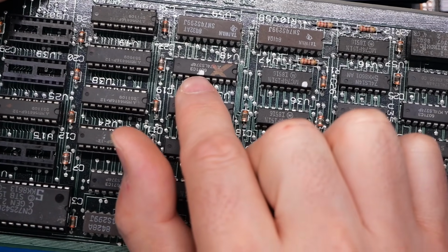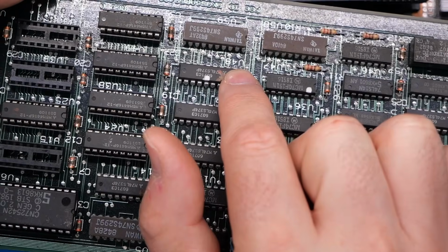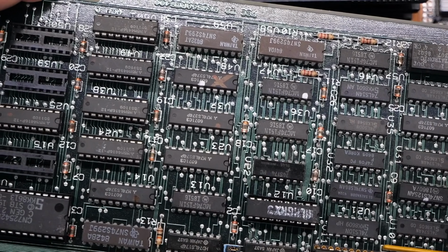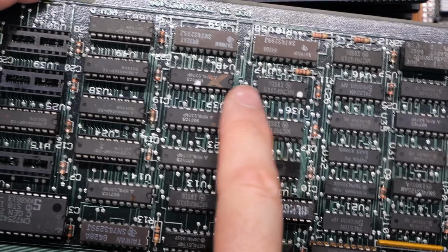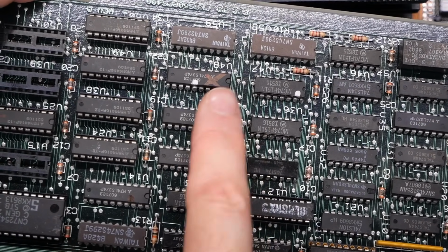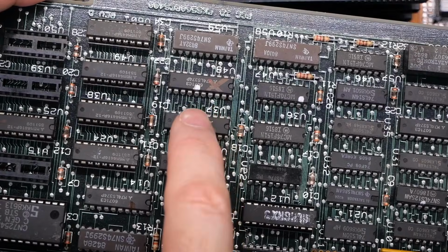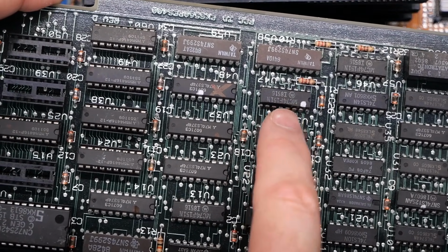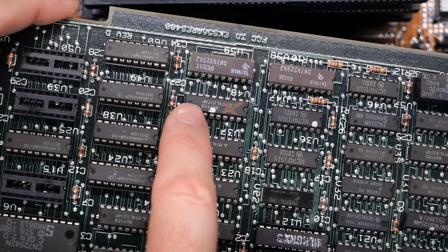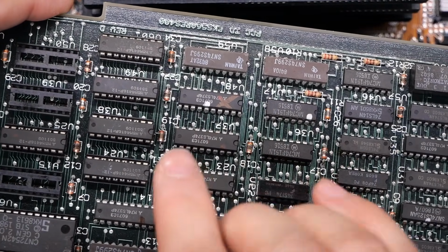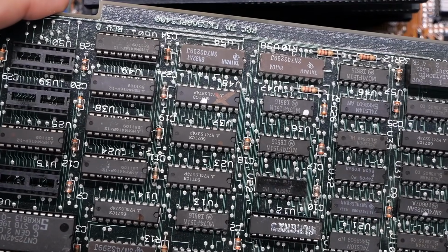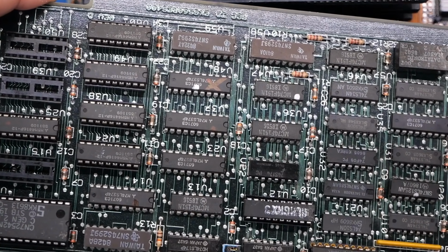One way we could actually test is cut the pin halfway up from the board, so you could probe the output of the flip-flop without actually removing it entirely from the board. That's just a good way to test, as long as you disconnect the connection between these two chips. If you're now suddenly seeing an output from the flip-flop, then that pretty much confirms it's this chip. It still could be a bad buffer driver that couldn't even drive the output of this, but that's unlikely in my opinion. You would still see some amount of signal, but we were seeing basically nothing, just barely any activity.